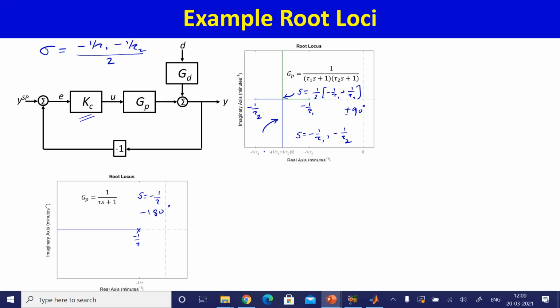However, please note that all real systems are third order or more, because any control system will have the process transfer function, the actuator or control valve transfer function, and the sensor transfer function. Each one of them would be at least a lag, so any real process will be third order or more. So these two examples are not really practical, just theoretical in nature.